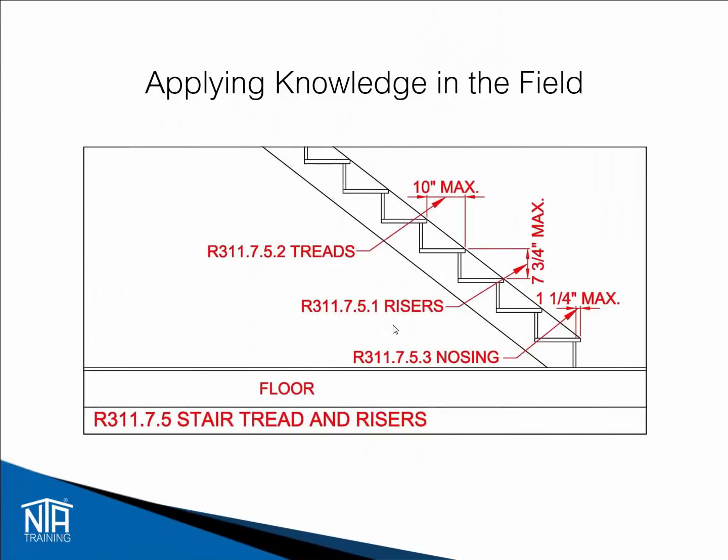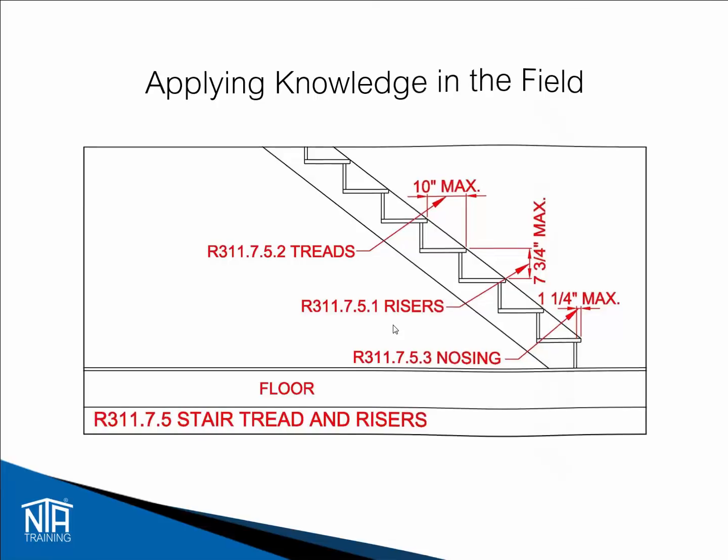This illustration shows the stair geometry required by section R311.7.5.1, R311.7.5.2, and R311.7.5.3. Keep in mind, many states amend stair geometry to their preference, such as Pennsylvania, where the required dimensions are 8 1/4 inches riser height and 9 inches tread depth.